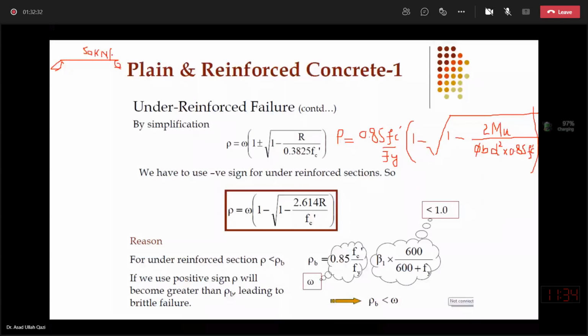So if this is the direct question asked, what you will do, since the beam is simply supported, the maximum moment demand will be at mid span, so you will determine wu L square by 8, 50 into 5 square over 8. That Mu you will put over here. Then comes the decision that in your beam, which fc prime and fy you are going to select.